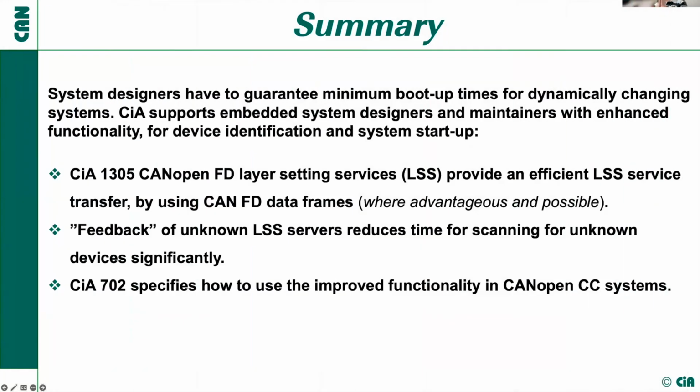Yeah, so much with regard to enhanced detection capability of dynamic added devices, so dynamic node ID addressing, dynamic network ID addressing. So as I've said, system designers have to guarantee minimum boot up times for dynamically changing systems. And therefore, we have now the documents here 1305, the CANopen FD layer setting services that provide an efficient LSS service transfer by using CAN-FD data frames, where it is advantageous and possible.